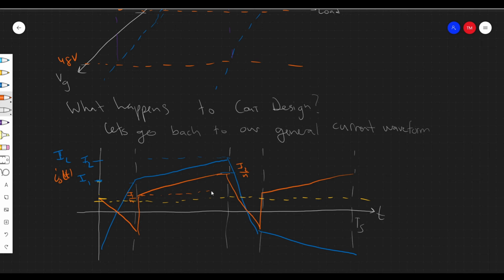And then we have to determine the charge sent to the output. So we kind of have three regions here now. Region 1, I'll call this delta Q2. We have another region down here. This is the rectangular region, which I'll call delta Q1. And then over here we have again a triangle, which I'll call delta Q3. And now the total charge that we have to determine is the sum of these three charges.